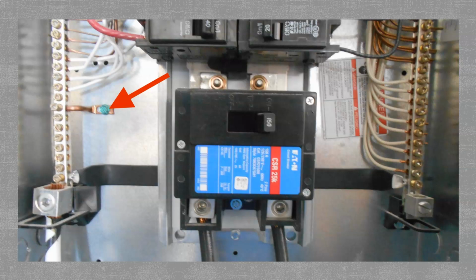Those are connected on the same terminal bar, and then off that terminal bar we have this jumper connecting the back of that bar to the disconnect means. So that tells us that this enclosure we're looking at is the main service disconnect enclosure. This is actually the disconnect for the service to this premise wiring, because we can see our grounded and grounding conductors bonded together, and we have that bonded to our disconnect enclosure as well.